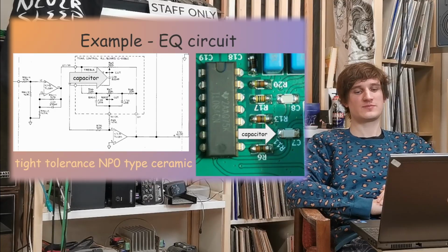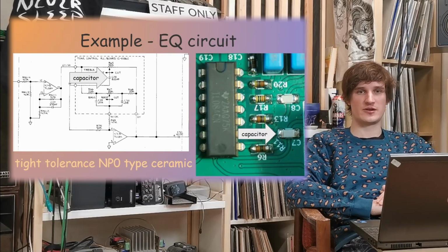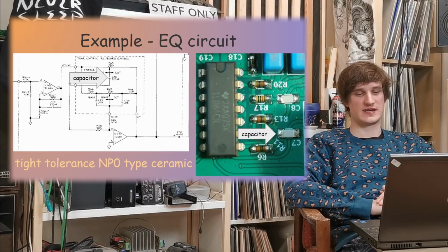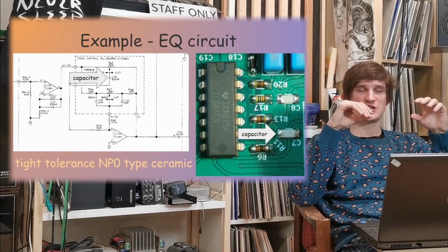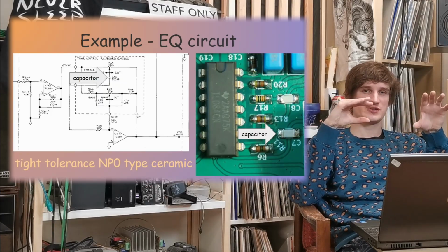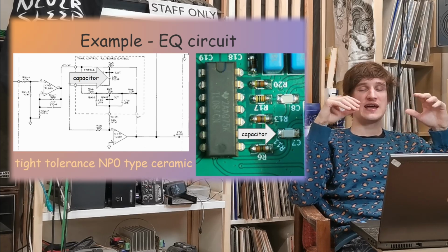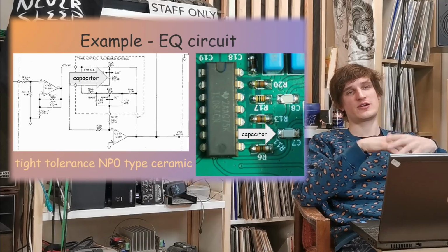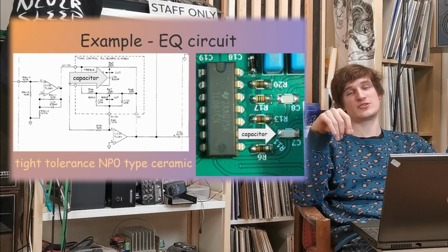This is very important because ceramic capacitors also come in X5R or X7R types, and they're completely not suitable for this application because their value can change with applied voltage, so they present nonlinear behavior. Also X5R and X7R ceramic capacitors can suffer from a piezoelectric effect.